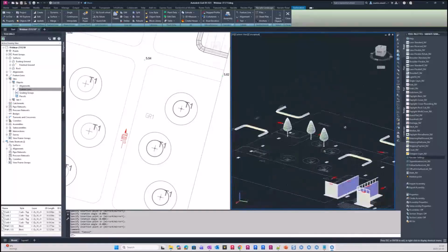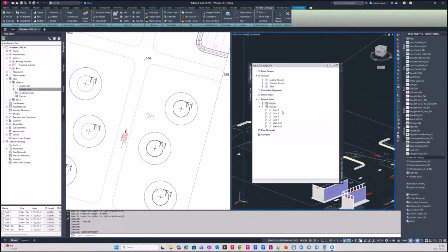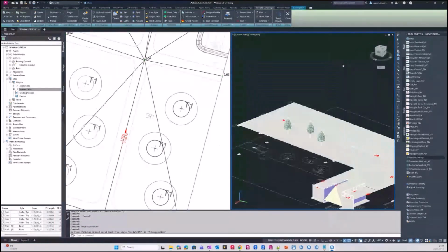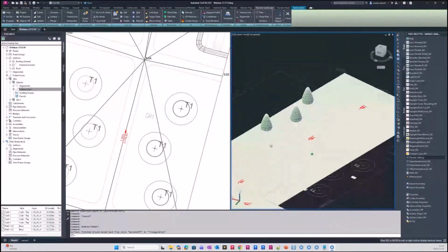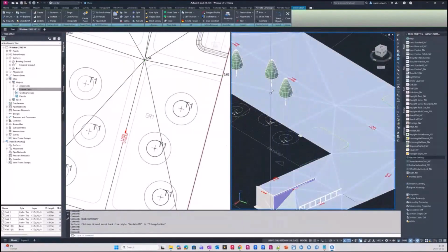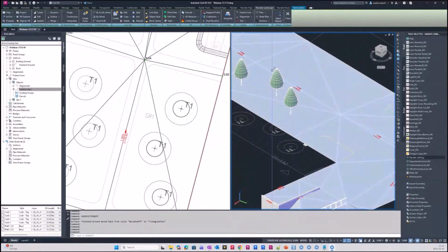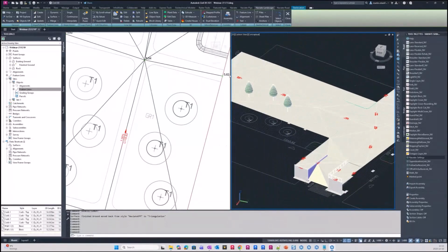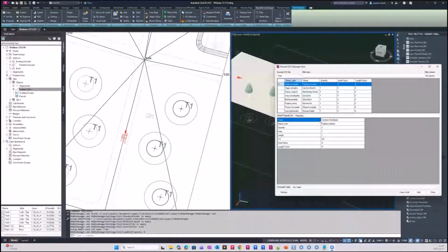So you can see how they attach to the surface. So got some trees here. And now, if I want to add property data on this one, I can use this plant data. And we got some list with trees that I will use. So I just pick one here. Use this one. And then I pick add.